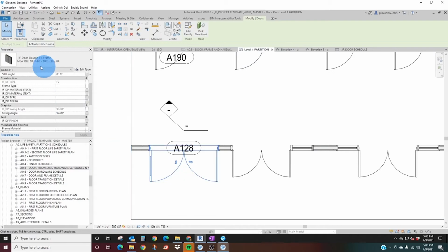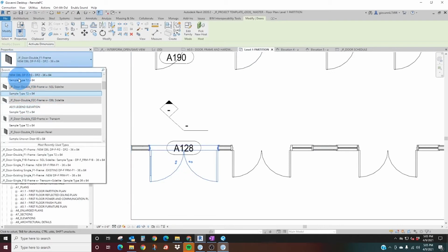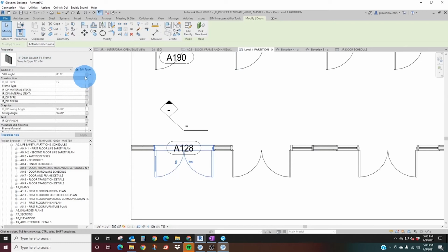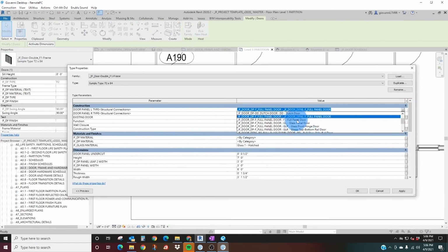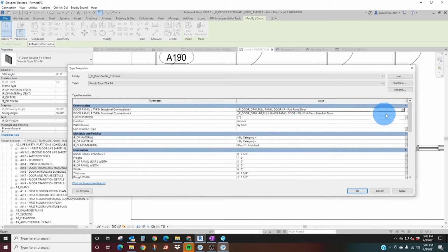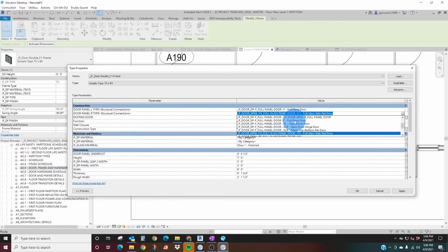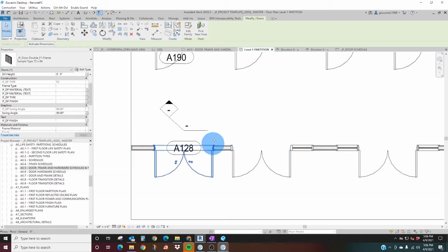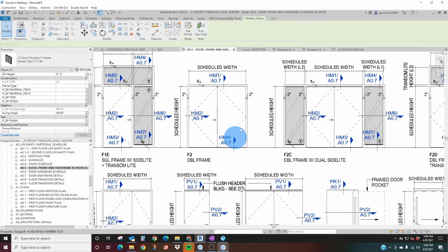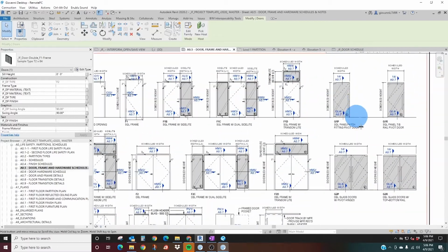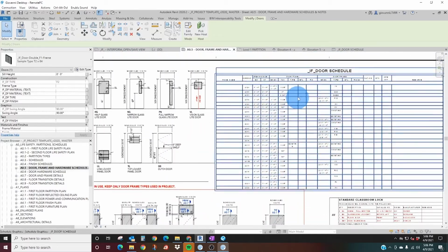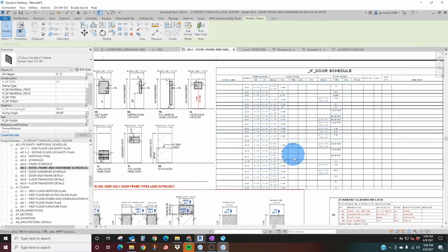So what I'm saying here, I'm speaking a little internally, but when I originally made this change, the sample type is the type that represents itself on our door elevation type. So that's another reason why we want this sample type to always be just left as it originally was, so that way we're not making undue changes to this door elevation. And you would just add in your door panel types into this column here.